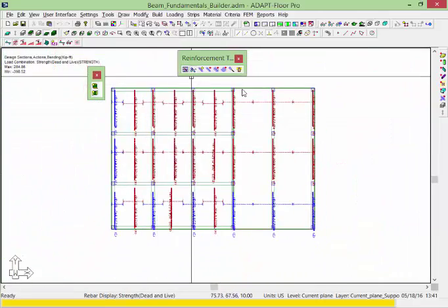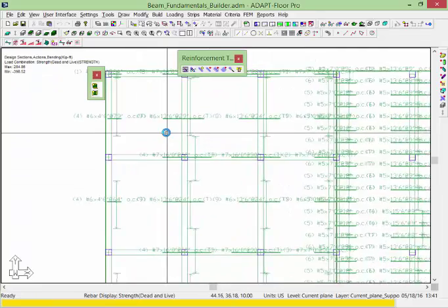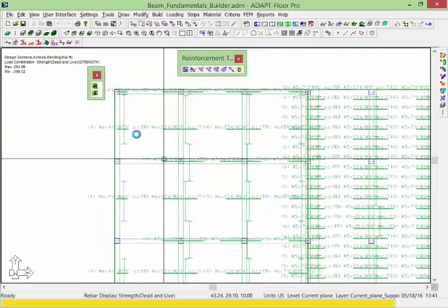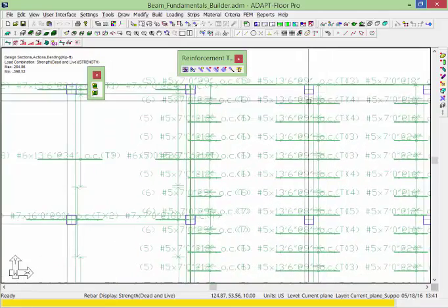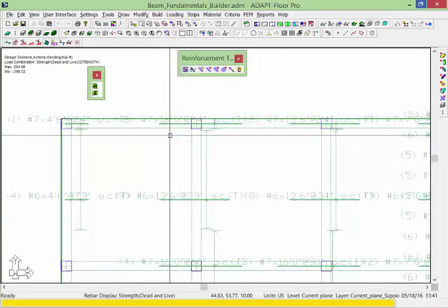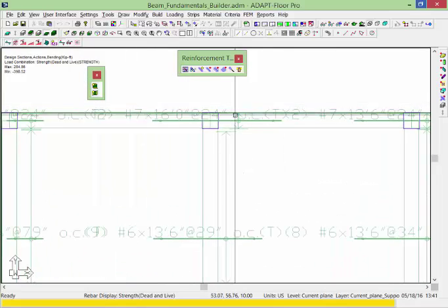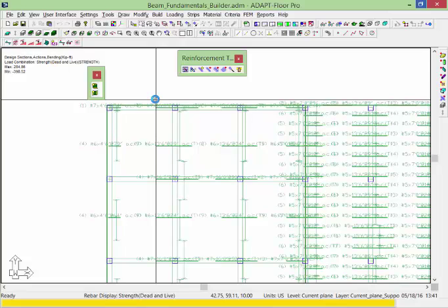We'll go back to the top reinforcement now. We'll go to the X direction top rebar. And the top rebar for an RC design in the program is typically shown as, again, distributed. So you can see the top bars over the beam are shown distributed, and because the slab and the top of the beam are at the same elevation, the distribution would just occur in the slab.